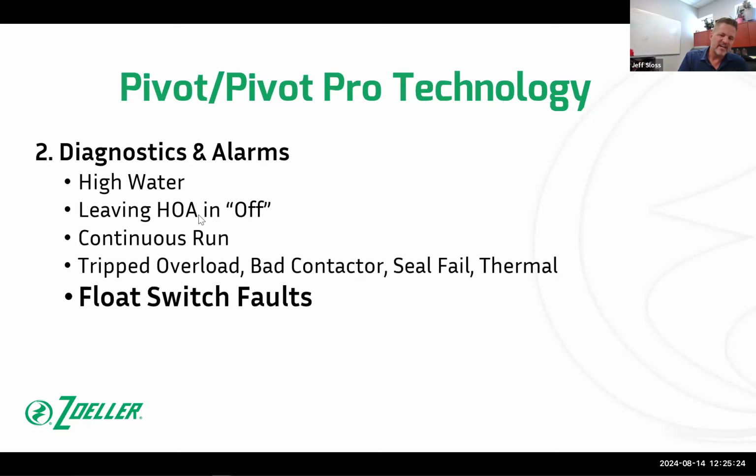When we give you a diagnostic, most panels are just going to basically be able to give you a high water alarm. They aren't giving you all the dozen or more alarms that we're doing. We're going to tell you, or not you, but the contractor, hey, you left the HOA, which is what tells the panel whether to be in hand, off, or auto mode.